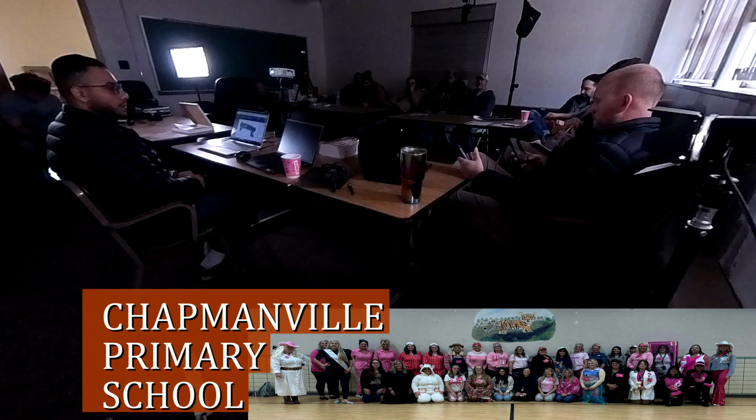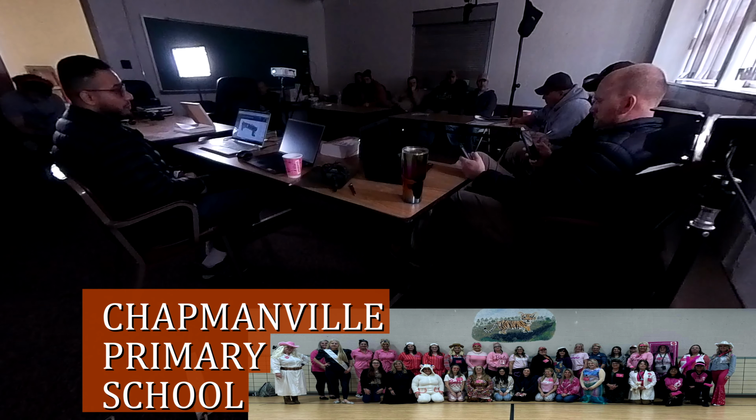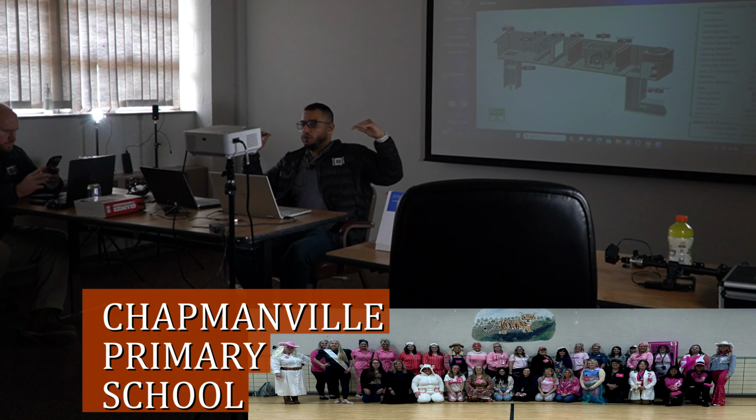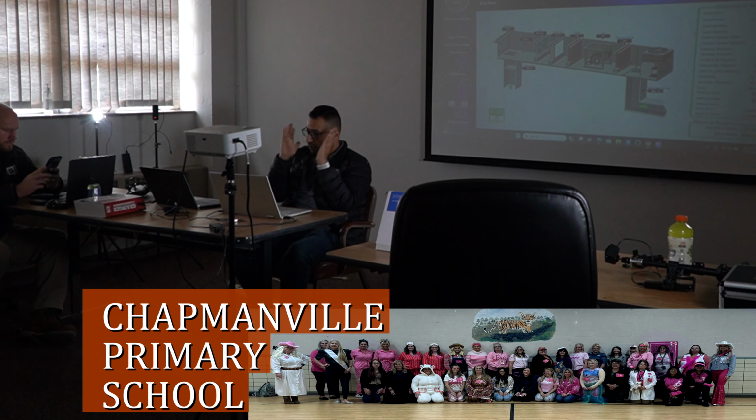Well, let me ask you a question. What should it be set on in the summertime? 72 to 73 is a very good space temp for the summertime. And there's the combination, like for example, if you're in summer mode and at the same time it's in override, the outside damper will not work. Even if it's overridden? Yeah, summer mode is supreme for the outside damper. It doesn't care if the unit is running or not running. It's strictly for the outside damper. So if somebody overrides that in the summer after hours, you're not going to open the outside damper.